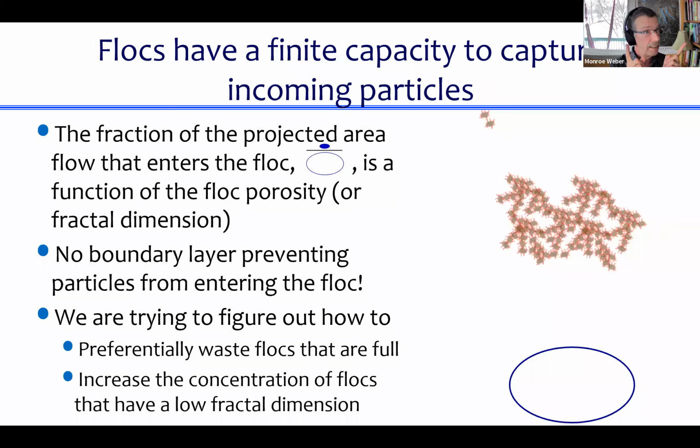Isn't that a great insight? So before we said this couldn't happen in the flocculator, but here the fluid dynamics are completely different. And so these flocs are not spinning wildly, they're just hanging out. And now this effect that water can actually flow through the floc, because it's no longer dragging all this boundary layer around with it, gives us this new mechanism for capturing little particles. Anybody else want to ask a question?